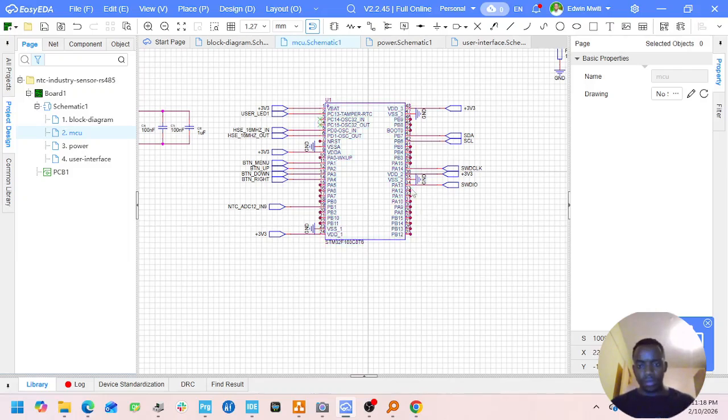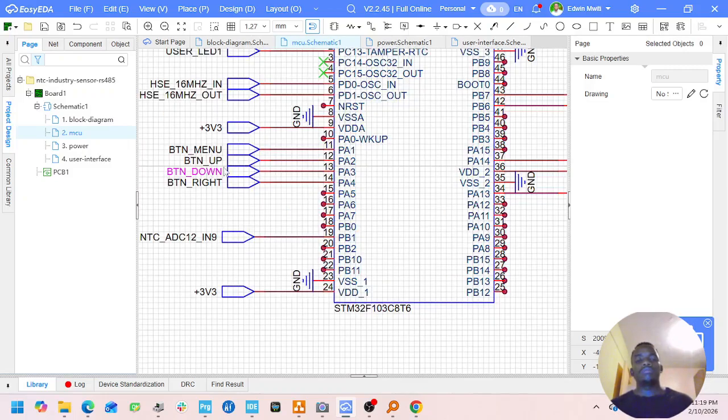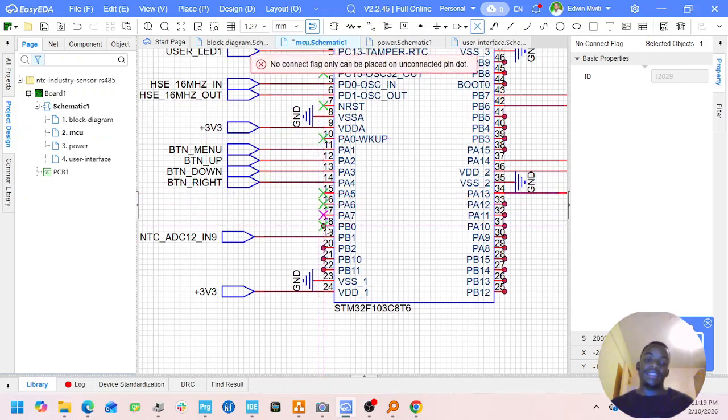But since this is a development device, we can always expose our programming interface. If you are doing an actual device that will go into mass production, don't expose your programming pins, because the user can easily read the program and can reprogram the device to do what is not wanted. Basically, you're just handing them off free, and these devices are always very cheap, especially a temperature sensor is super cheap, right?